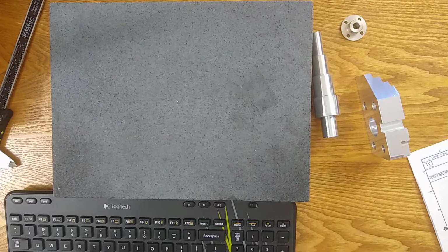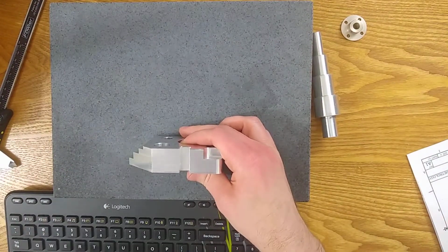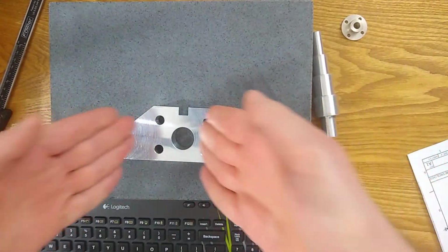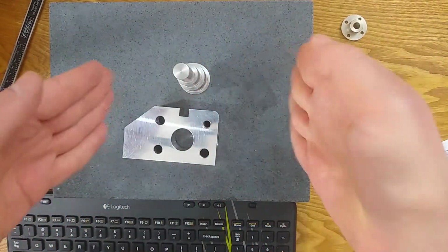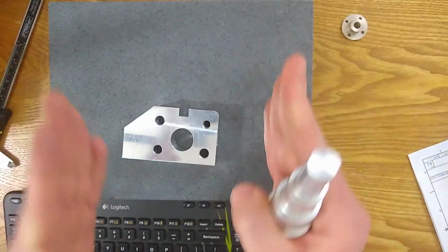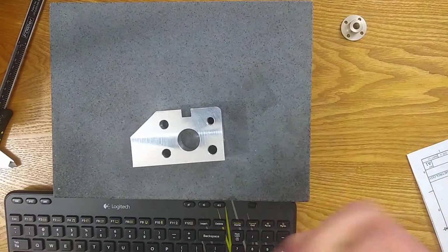So feature control frames override the basic dimension of tolerances. Here are some examples, and they're not all position, they involve some of the other symbols, but rectangular zones become circles. A waviness in a part, up or down, becomes restricted to a flat or a parallel section. A taper or a skew on, say, a hole, could be a hole that tapers inward, or some sort of diameter that tapers in one direction or another. Sometimes those are restricted to a perpendicular or a parallel zone. And size and position can be restricted to certain shapes.